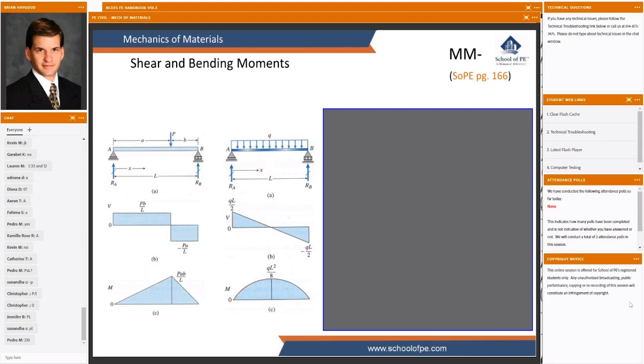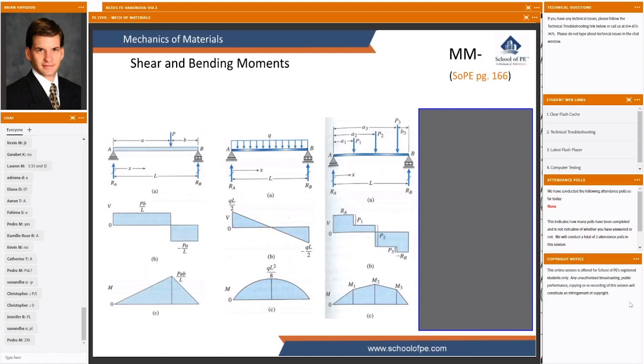The next example they gave us here is not all that interesting. It's a series of point loads. Every point load is a discontinuity or infinite slope region on our shear diagram. And in between those discontinuities, we have a uniform slope here because there's no distributed load, so we have no slope. This slope of RA gives us a slope here, and then a little less of a slope there, a negative slope here, and an even lesser slope there. Where the shear diagram crosses 0, we do have a local maximum on our moment diagram as predicted.